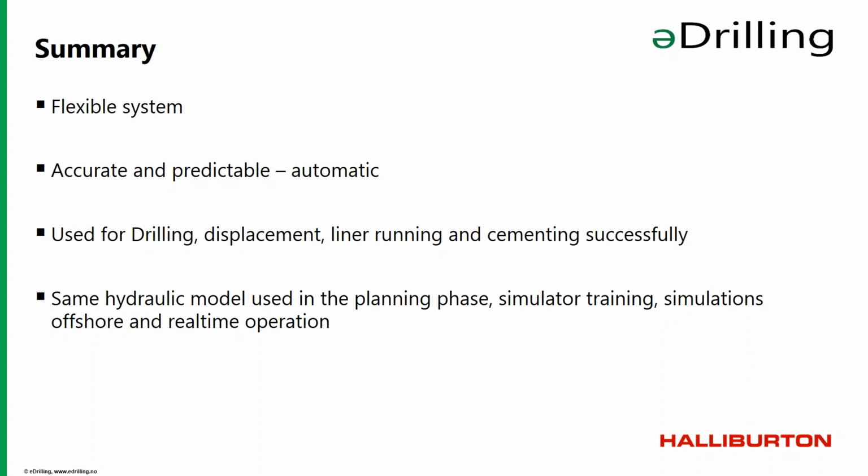So what you then do is design a lower mud weight, which is statically underbalanced, by adding the pressure on surface with a choke. You would be in overbalance, and then you would be able to drill through the tight margin.